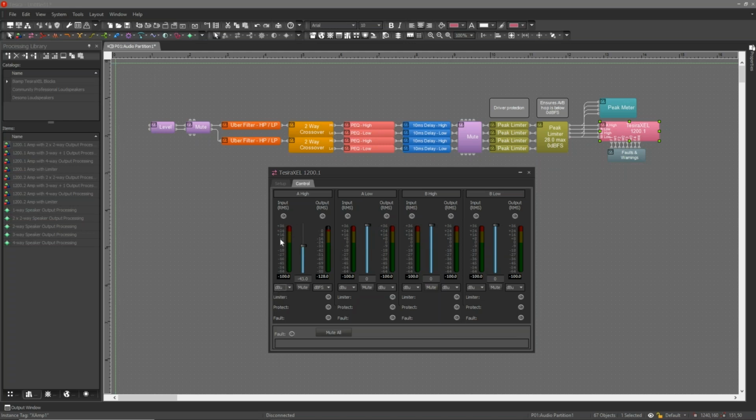The difference is the notation on the left. The meter will continue reading in the exact same spot. It doesn't matter which notation you're using. What is important to know is 0 dBu is equal to minus 24 dBFS. So we'll see that populate in a live amplifier.